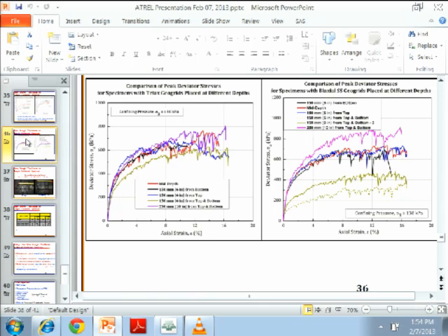Yes. So the concept of incremental collapse, or the shakedown concept, is not captured within those 10,000 cycles in the lab with the same standard procedures. You can rank with and without grid, but it's not exactly related to the life performance of that ballast layer for a 2-inch deformation settlement in the field. Yes. But you can relate the two, although they're not the same. So that should be your explanation.